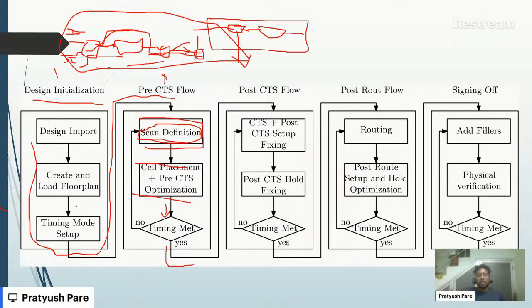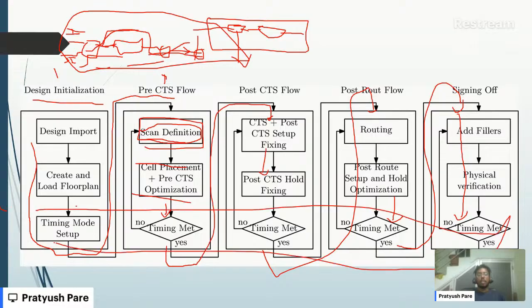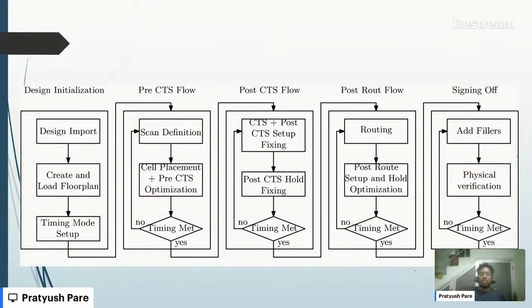After the timing is met, we go for the CTS and do the CTS flow, and then do the timing again and fix it, and if it is fixed then we go to routing, and then again we do the timing. So Vivek, you were saying, right, that timing means STA is very important. As you can see, at every stage you will have a timing check. So STA is very important for us as an engineer. This was just a nutshell of how the flow in ASIC works.